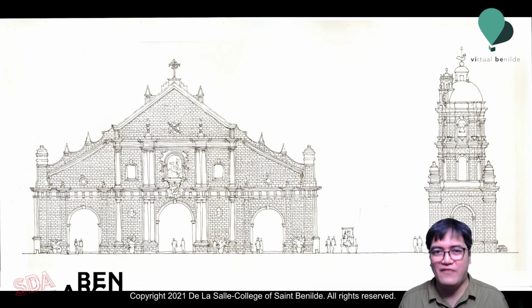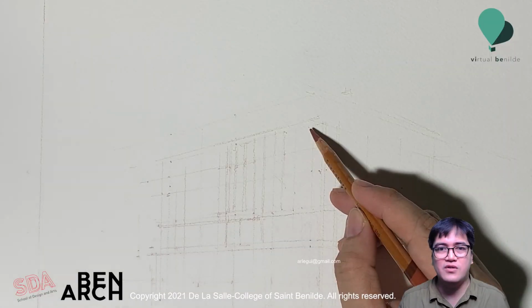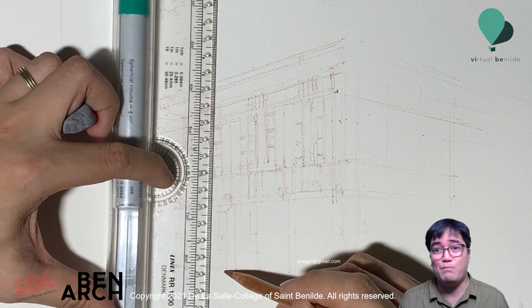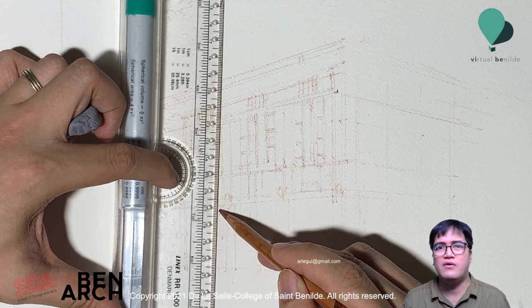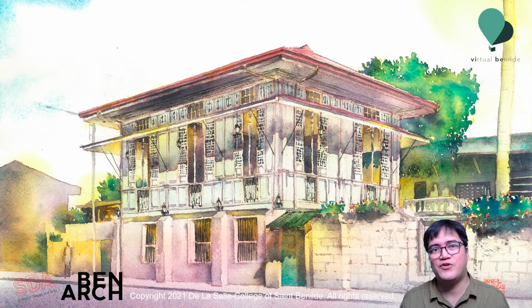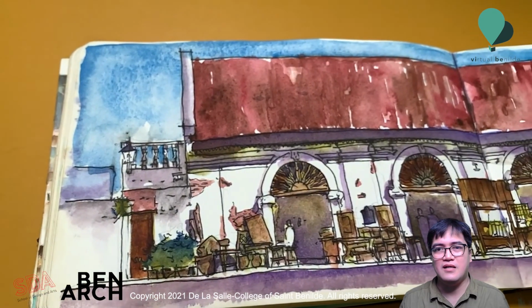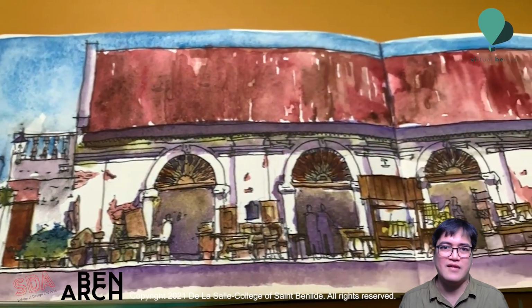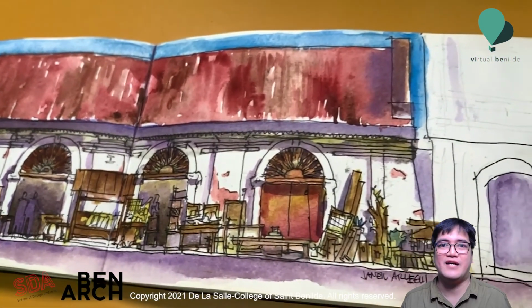This is a flat frontal depiction on one face of the building. Unlike how you would actually perceive the building in perspective, elevation drawings have no diminishing nor converging lines, nor foreshortening elements. This is straight up like a rectilinear drawing of the front facade, like how you would see them on proposed building drawing sets, meaning the building's horizontal and vertical lines appear as true horizontal and true vertical lines.